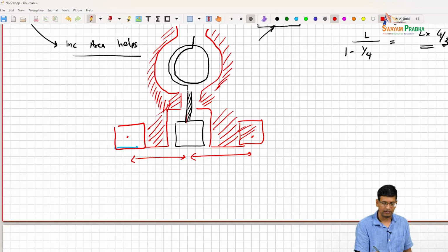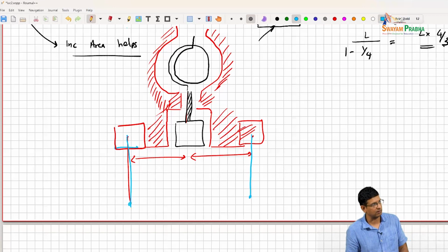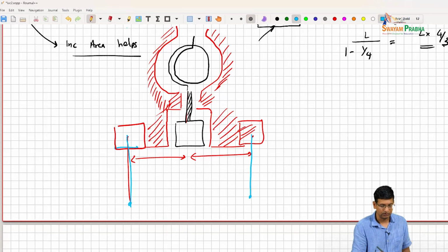Because the signal and ground are quite close, but eventually when you are making contact on your board, on your wire bond, on your bumps, flip chip, whatever you do, there is discontinuity here, right? And the only way to do it is actually to model discontinuity. So let's say that you're doing a flip chip.